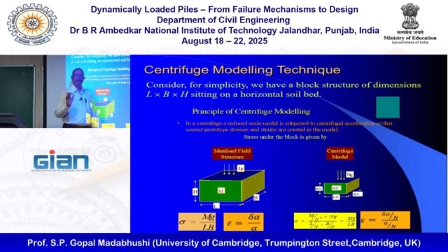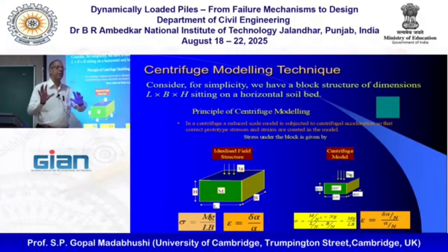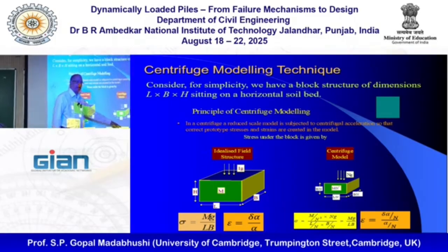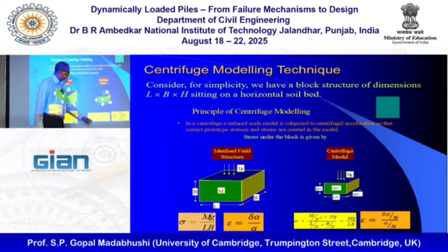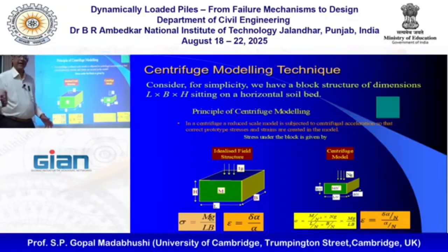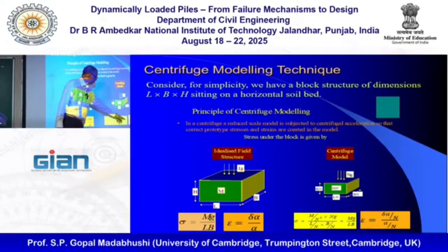Now, just for a minute, let's imagine that we're going to put this block in a gravity where gravity is n times bigger. G is your acceleration due to gravity, but for this block, we somehow will make it sit in n times the normal Earth's gravity. If you can do that, let's calculate the pressure this block is going to exert. So the mass is m over n cubed, the gravity is n times g, length is L over n, breadth is B over n. And as you can see, all the n's cancel out, and I recover exactly the same stress, mg over LB.